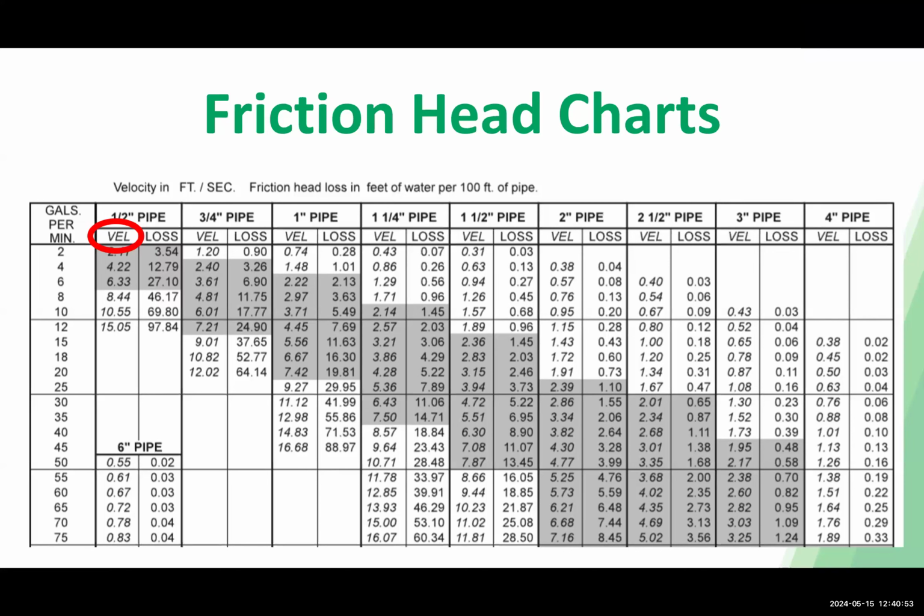I'd say it's going to completely depend on the system. If, like you said, it's pumping up 10, 20 feet or something, and it's going to gravity after that, that length of pipe is not very long. But if you have a system that may have something like over 1,000 feet in length, and that's not a hard number, I'm just using that as an example, I would say it's important to take that into consideration because, as I'm going to show you in some of these calculations, the longer that run of pipe, there's a whole lot more friction, or a whole lot more pressure that's going to be put on that pump from that additional friction loss.